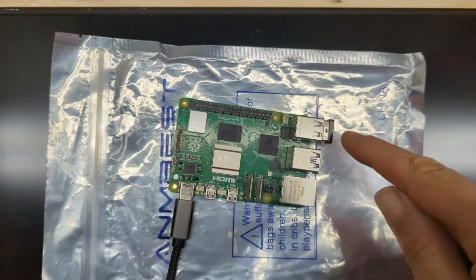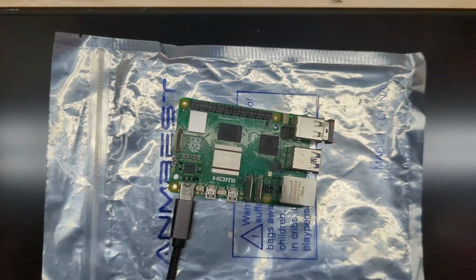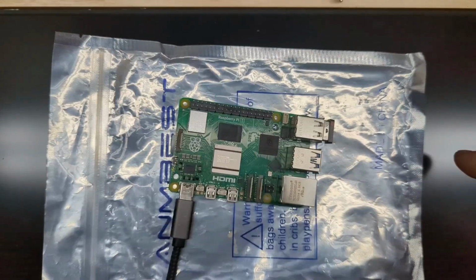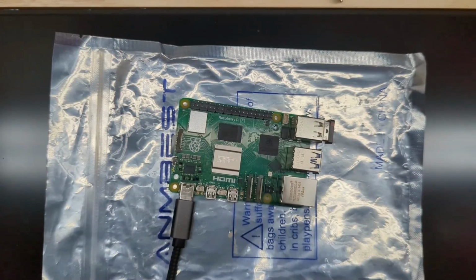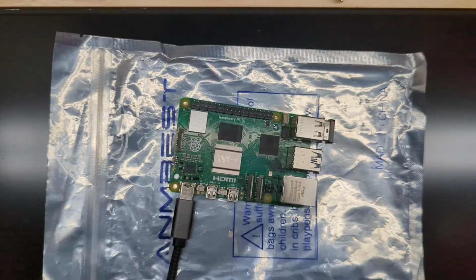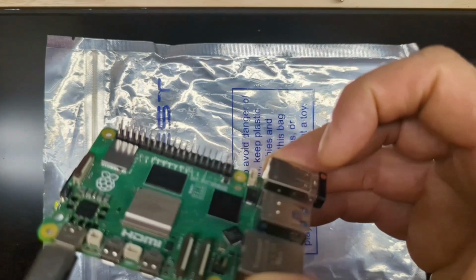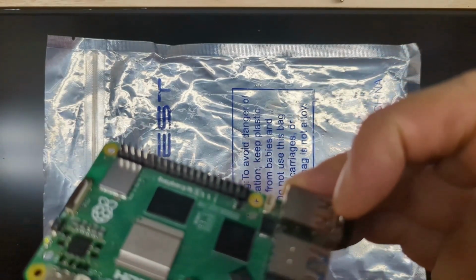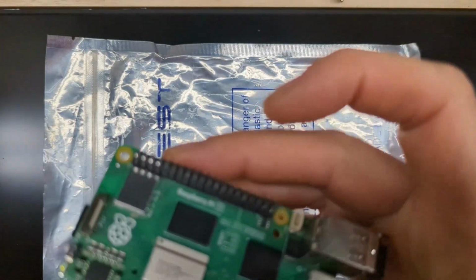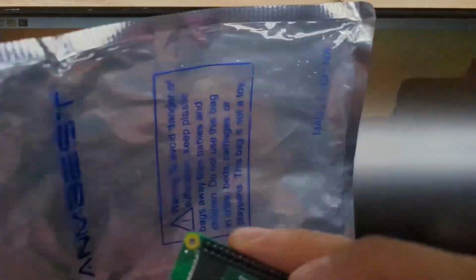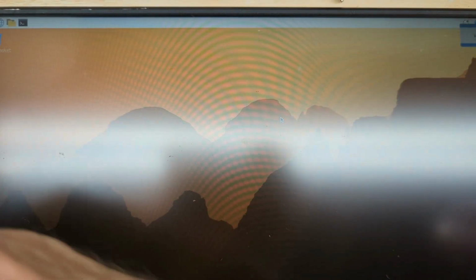I've got a Bluetooth transmitter connected to the USB port, and then we have this monitor that's sitting right below this, and it's just an HDMI connection on the monitor. You have an HDMI output on the Raspberry Pi. You just have to make sure you have the right connectors, because the Raspberry Pi HDMI port is a micro HDMI. So we will go ahead and connect the micro HDMI port, and then make sure you have the connector facing the correct direction. Push that in. And then you see the monitor just lit up behind it.